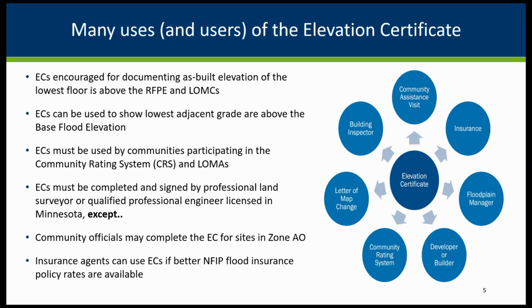Touched on some of this, that it is encouraged for documenting the as-built elevation, especially for those lowest floors, and making sure it's above the regulatory flood protection elevation, and for letters of map changes. The elevation certificate can be used to show that lowest adjacent grade, and that base, it can be used to document the base flood elevation that was used.